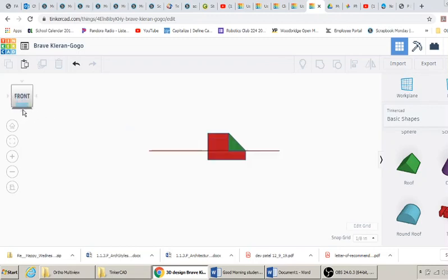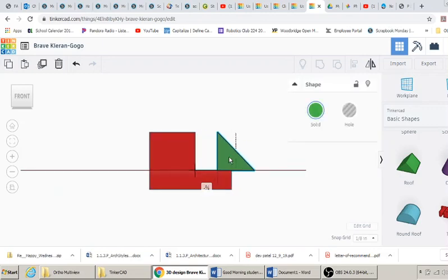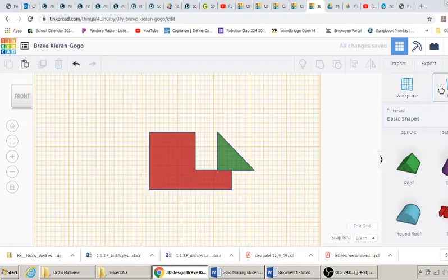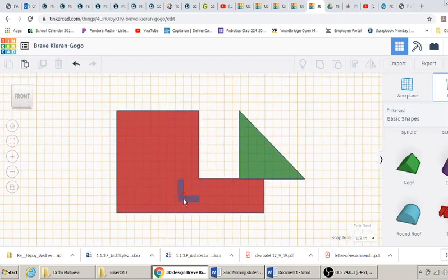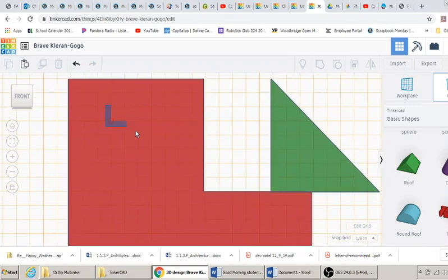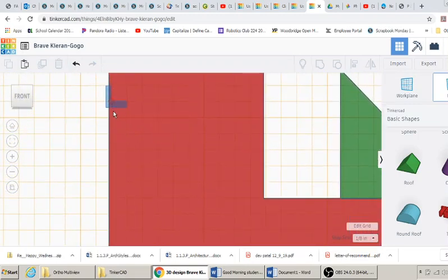So we're going to go to the front view, orthographic, and I'm going to pull this away, and I'm going to show you the ruler tool and how helpful that could be. The only reason I can't use a ruler tool is I have to change my work plane to this surface. There we go. Now grab the ruler tool, zoom in, and first confirm are my objects aligned with the grid? And you can see that it's not.